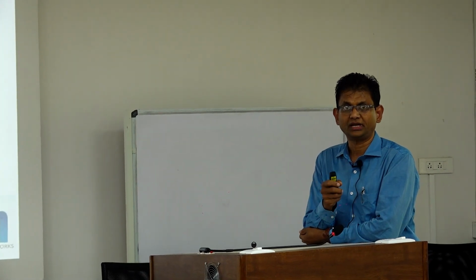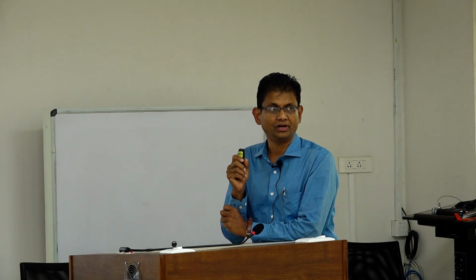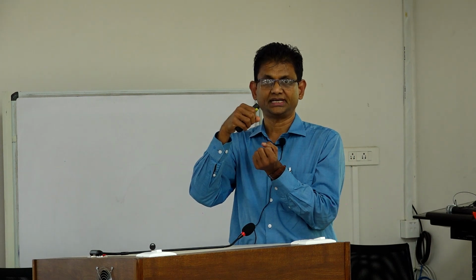As I said, all those processes in optoelectronic devices are based on excitons. You might have already heard what an exciton is. An exciton is nothing but a bound electron-hole pair. When light hits the semiconductor, the electron goes to the conduction band, leaving a hole, and the electron and hole are still bound, not separated. That is called an exciton. After diffusion, the exciton will dissociate and separate into charges.